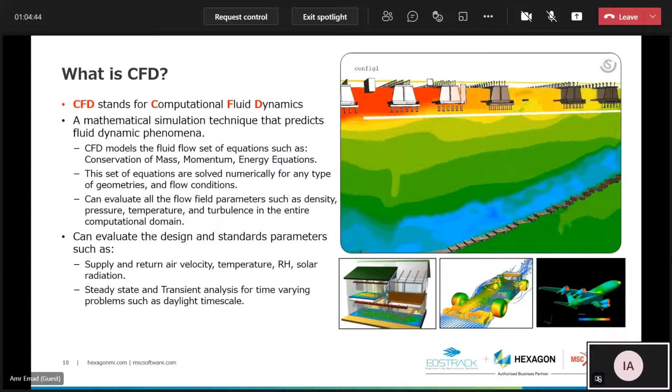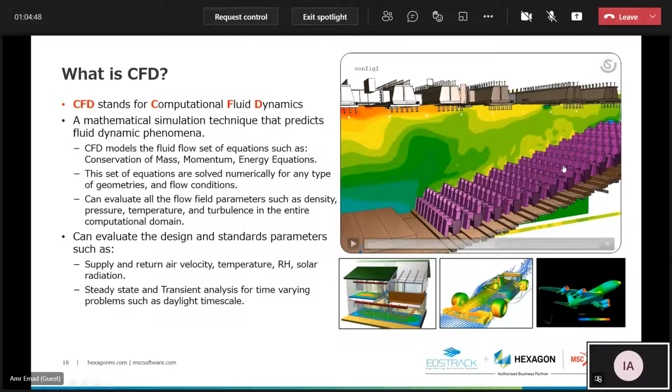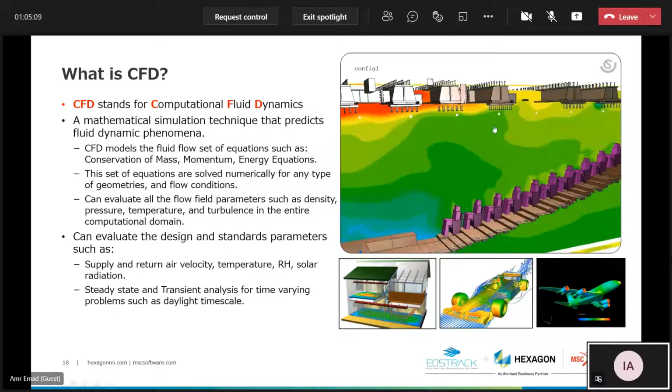How to picture this? This kind of visualization and judgment of the flow field inside the theater, for example, can't be judged only from certain calculations that do some mass balance on the inlets and outlets. This cannot be pictured with such a code, and you have to employ some 3D code to visualize each point inside this room or theater, and how it functions according to the thermal comfort standard.